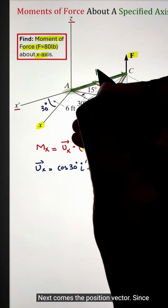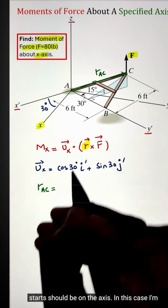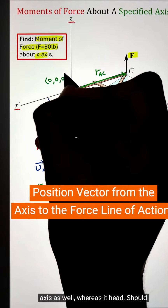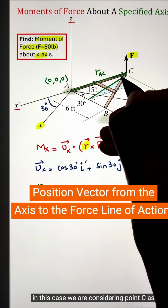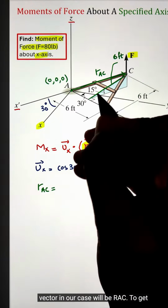Next comes the position vector. Since the position vector should start on the axis, in this case I'm selecting point A as it lies on the x-axis, whereas it should end on the line of action of the force. So in this case, we are considering point C as that head. So the required position vector in our case will be r_AC.